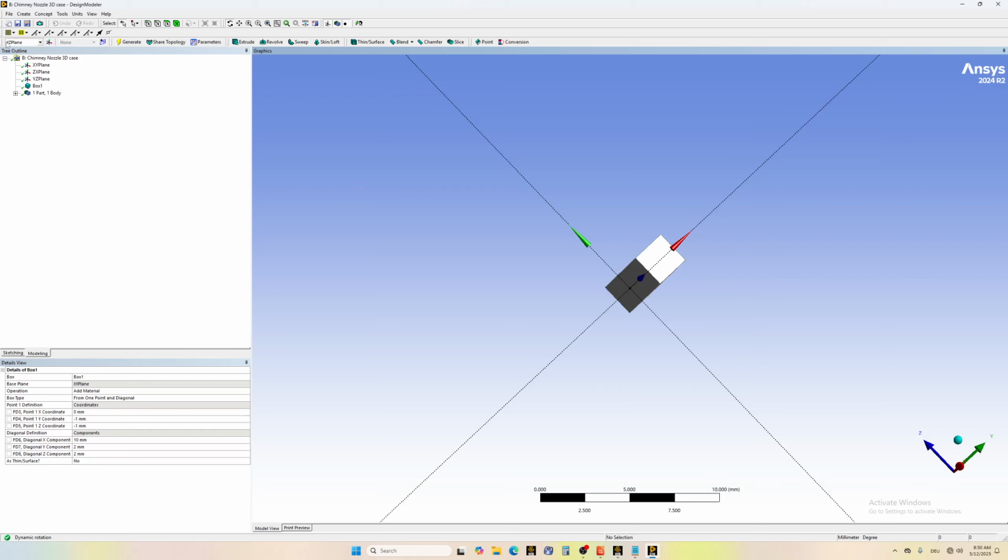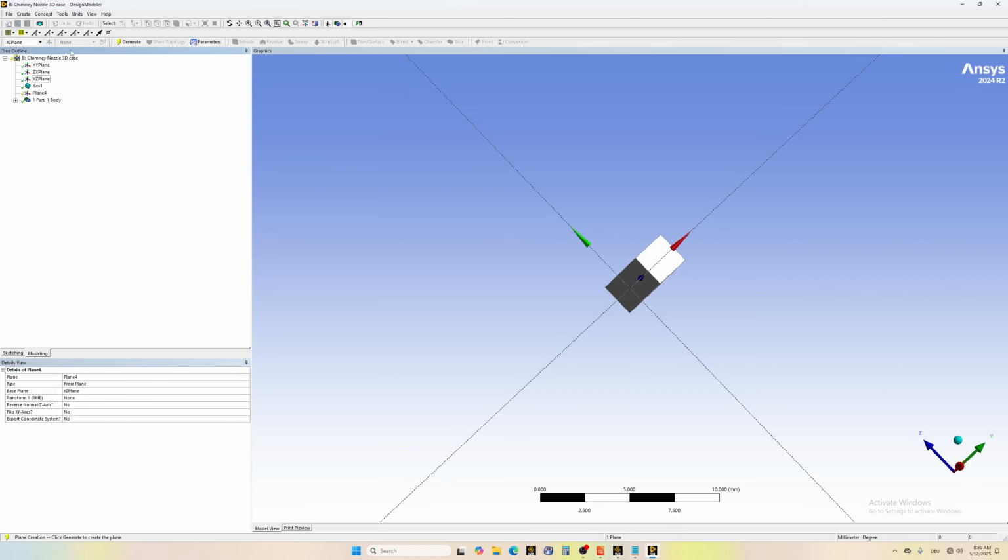Alrighty, so we choose here the YZ plane, so you can click here or you can choose the plane here, new plane, click on it. All right, and now let's transform. Actually the only transformation that we will do is offset Z. Don't worry about this one, you can always go back to make changes if you chose the wrong settings.